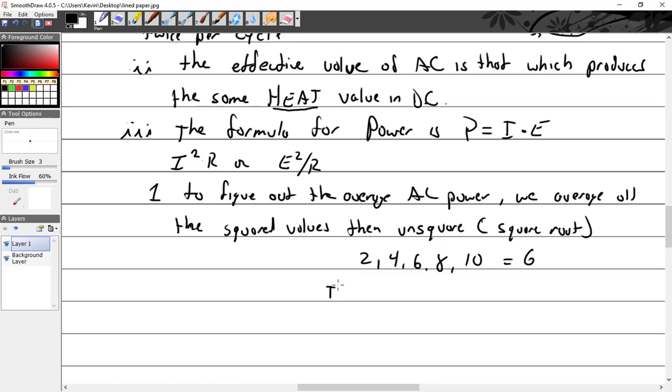Okay, the RMS. So if I square them all, then add it, then divide, that's root mean squared, it is going to be 6.63. It comes out at a different number. It is actually more accurate.